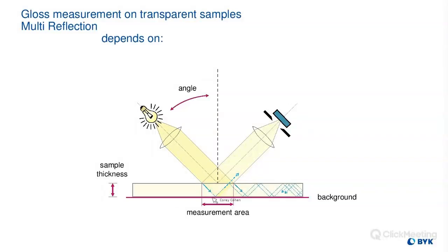Now the background or backing is another consideration. You need something opaque, something solid to take your measurements against. For that, we recommend a black matte material. We want the most non-reflecting material possible, because we want any light that's getting into the detector to be gloss that's reflecting off of the material you're actually testing and not off of the backing.